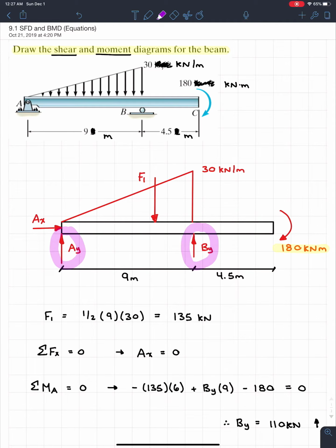We're going to have to find a number of equations, one for each segment. A segment is a part of the free body diagram where the forces don't really change. For instance, if I wanted to analyze this segment right here, as well as this segment right here, I make two cuts of this beam and analyze the left side of both of these cuts.